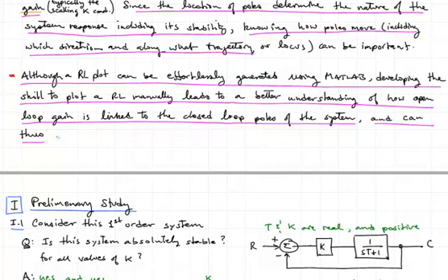A lot of times that's qualitative. We won't look for the root locus to give us exact quantitative results, because at that point it's easy to use a computer program to help us. But in a problem where the solution space is really wide open, and we can put a compensator in our system that has poles and zeros anywhere, how do we narrow that down judiciously, thoughtfully, without having to just entrust everything to a computer doing trial and error? So that's what the root locus is really about.